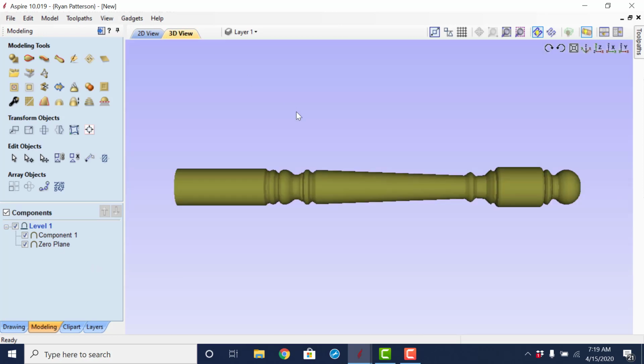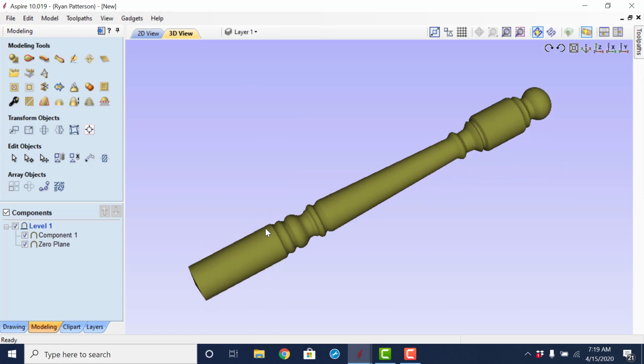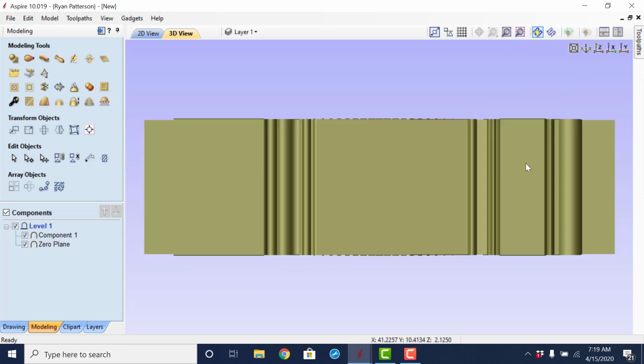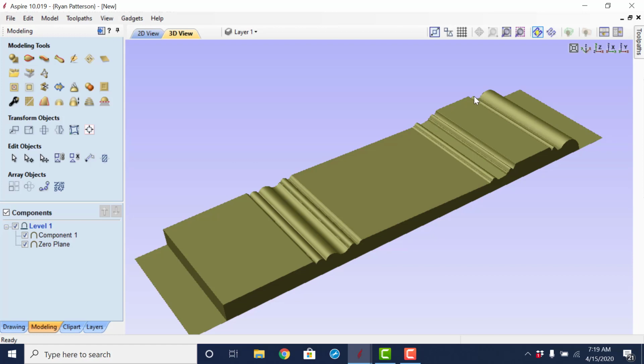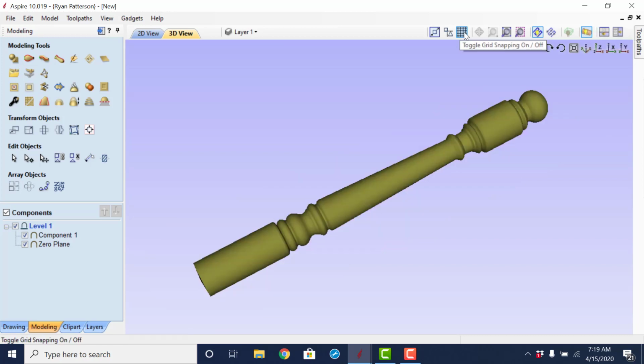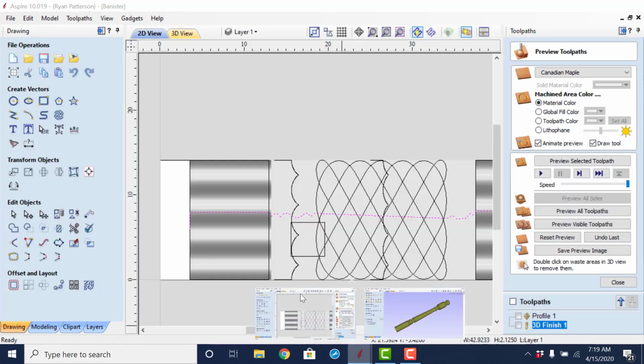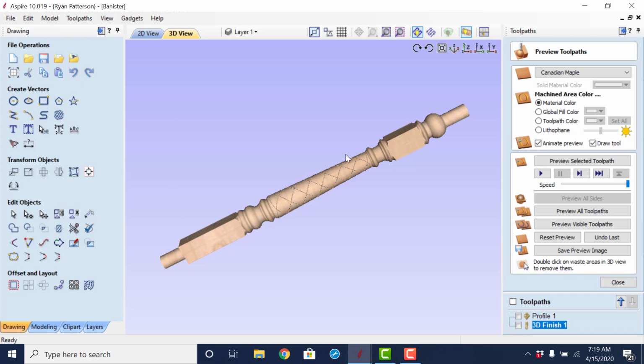Going to the 3D tab, we can see that we now have our radius block here, and to see what this looks like unrolled, we could just simply click that unwrapping, and we basically have what you've probably done already, which is a flat three-dimensional object. We will roll that back up. Our next steps are to create the square top and the square on the bottom, similar to what we have right here.